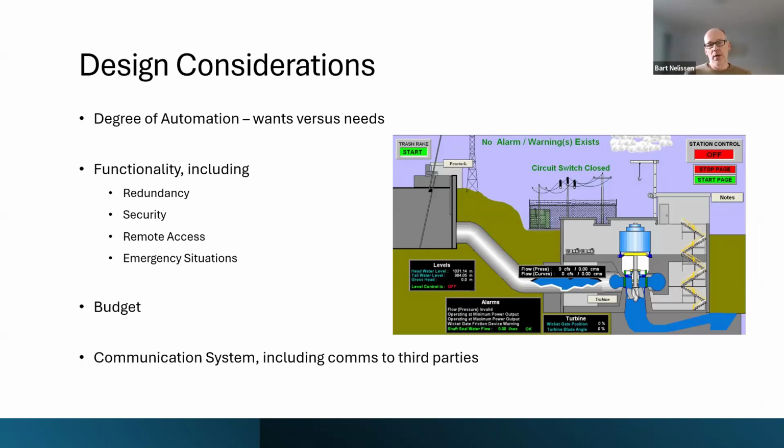I've put four on the screen, and I also put a picture on the screen of what, may I say, an older style process graphic looks like. I say older style because more current guidelines in the industry have indicated that graphics such as what you're looking at right now, being very colorful and very busy, are not necessarily the most productive graphics for an operator to use. The reason is that it is too cumbersome and too hard for an operator to determine what's right and what's wrong on this graphic.